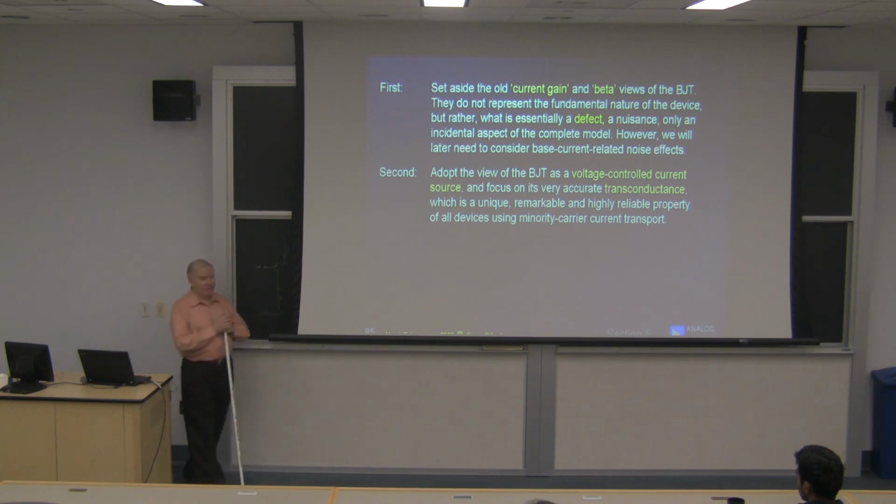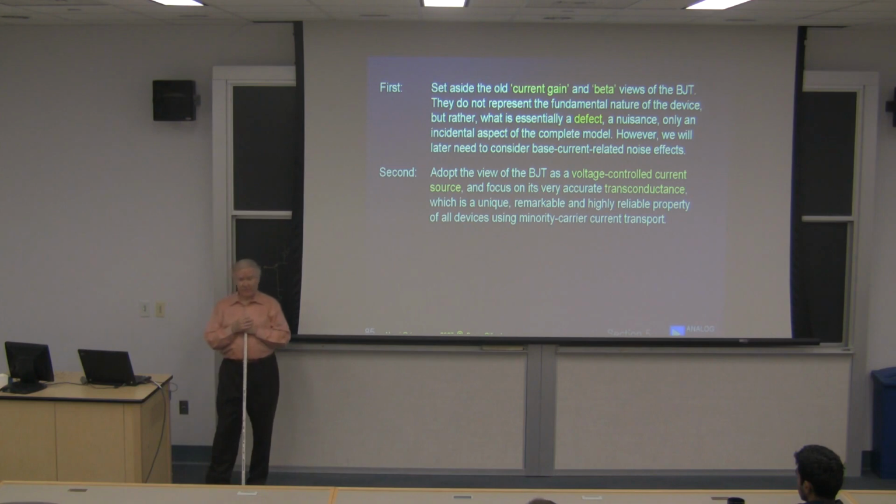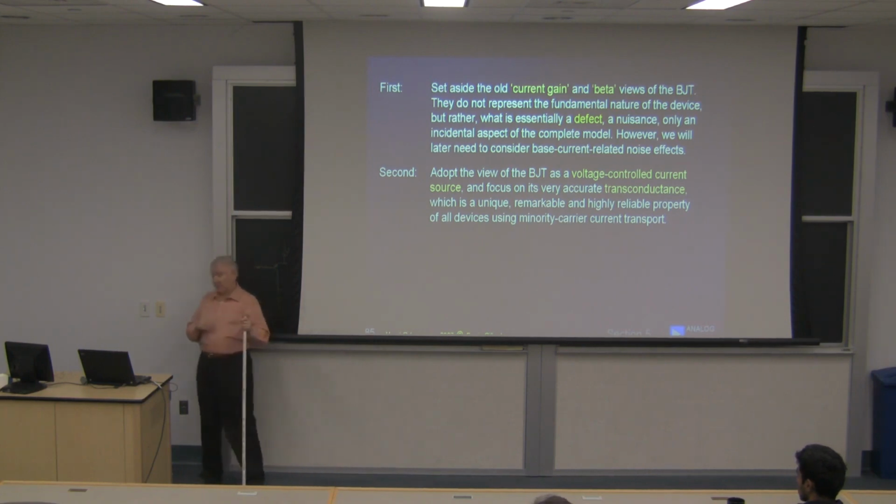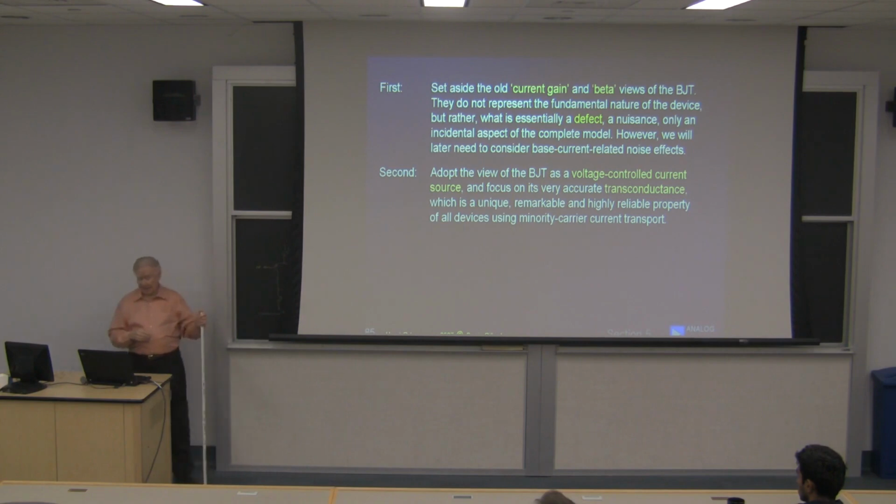I'm not talking about tunneling. I'm talking about the AC current in the gate of an MOS transistor, wherever you're trying to do things at frequency. That gate presents an impedance that is a reflection of the gate resistance coupled with the gate capacitance, a complicated impedance. But it's there nonetheless. I think the BJT is a bit more troublesome in this regard, but focus on its transconductance.